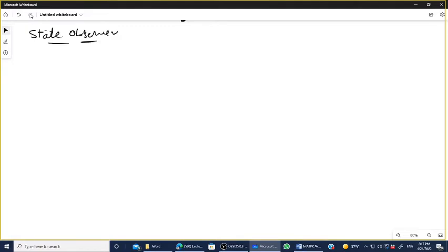and you can find out the gain matrix K. But as you know, when you are going to apply this theorem, first of all you have to ensure that your system is completely controllable. Completely controllable means all the state variables are available at the feedback. In the pole placement design, in pole placement techniques,